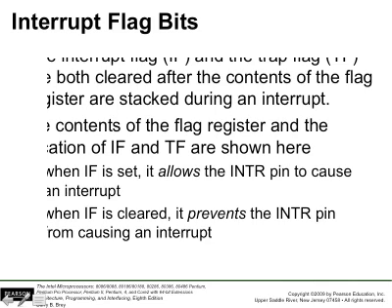This IF flag is inside the processor itself. It's a register that we can access. We can set or reset this bit. If we set this IF flag as 1, that means we allow this microprocessor to respond to interrupts. If we clear this bit, that is to say, we do not let the processor respond to this INTR pin.